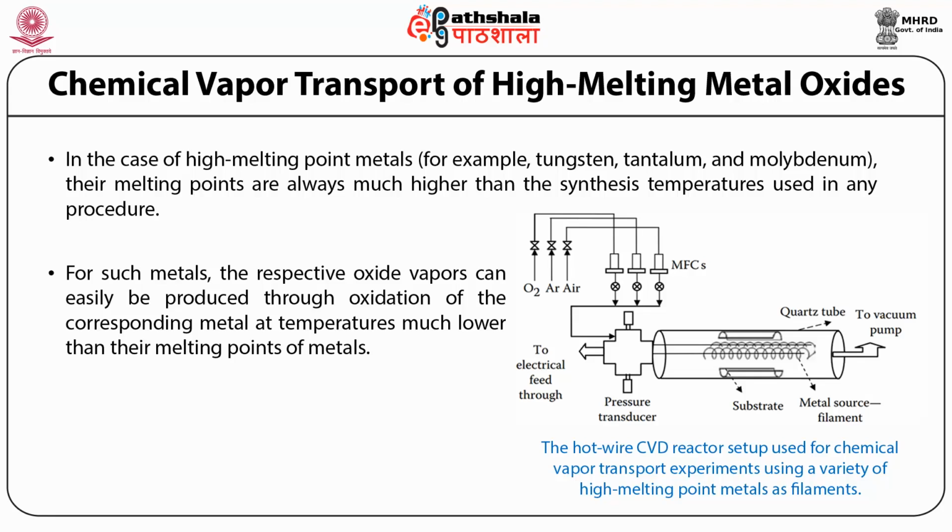In addition to the oven, the radiation from the filaments can heat the substrate to high temperature depending upon its distance from the source. The substrate can be easily heated up to a temperature around 500 to 550 degrees Celsius in a 2-inch quartz tube without the use of external heating via furnace.